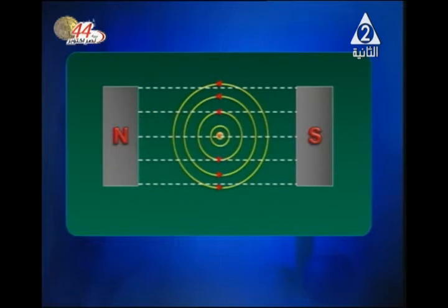We've got a magnet, and the field of the magnet is uniform. What does it mean the field is uniform? It means it is composed of straight flux lines which are equally spaced. And we've got a wire carrying current. Current is moving out of the screen. The two fields will interact. On one side of the wire, they'll have the same direction. On the opposite side, the fields will have opposite directions.